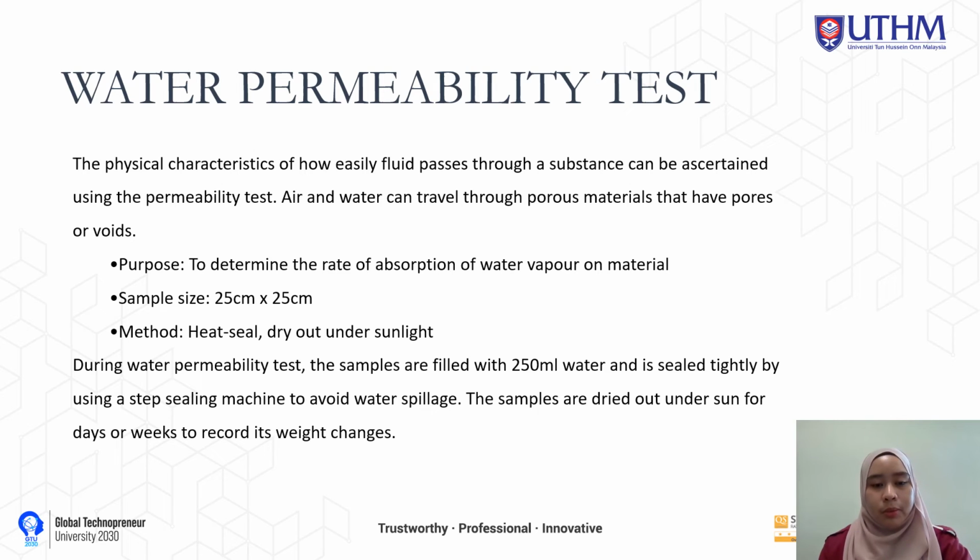During the water permeability test, the samples are filled with 250 ml water and sealed tightly by using a step sealing machine to avoid water spillage. The samples are dried out under the sun for days or weeks to record their weight changes.